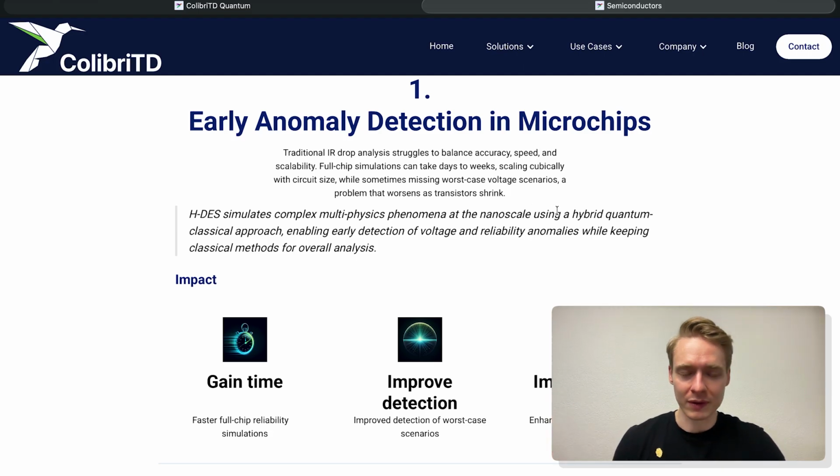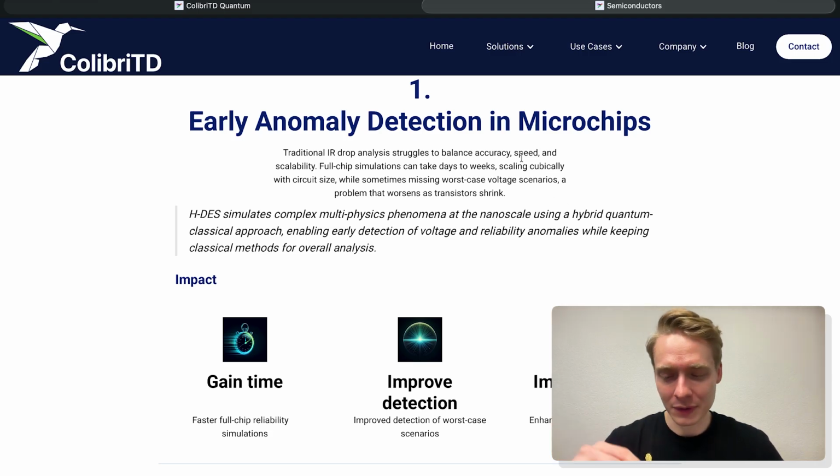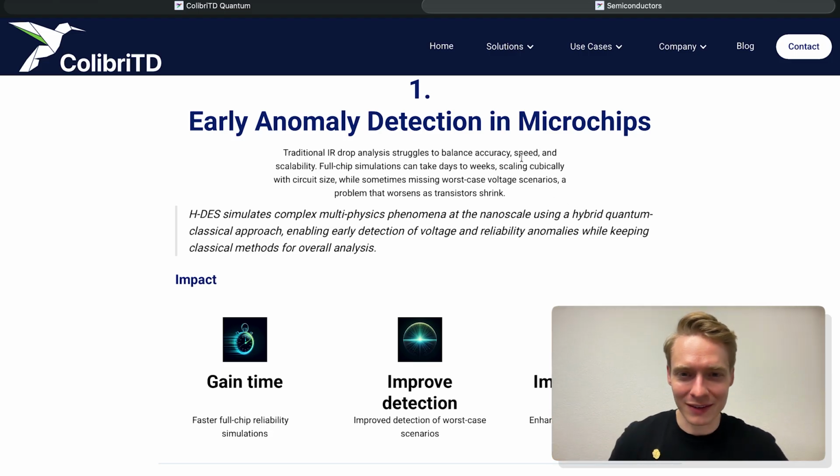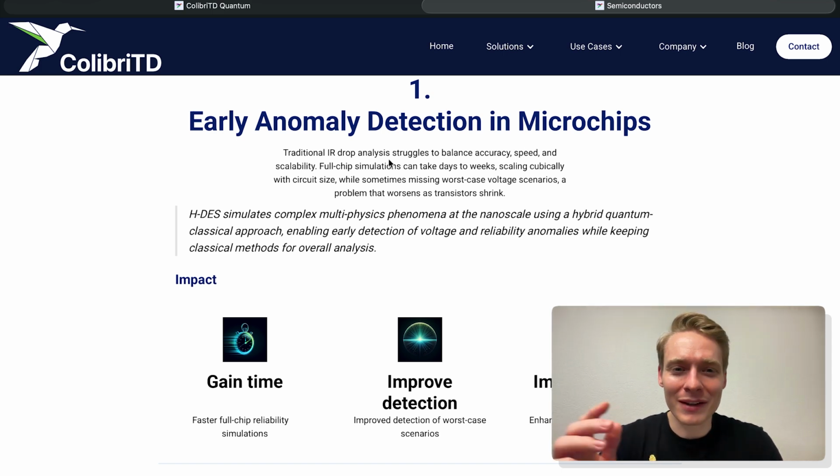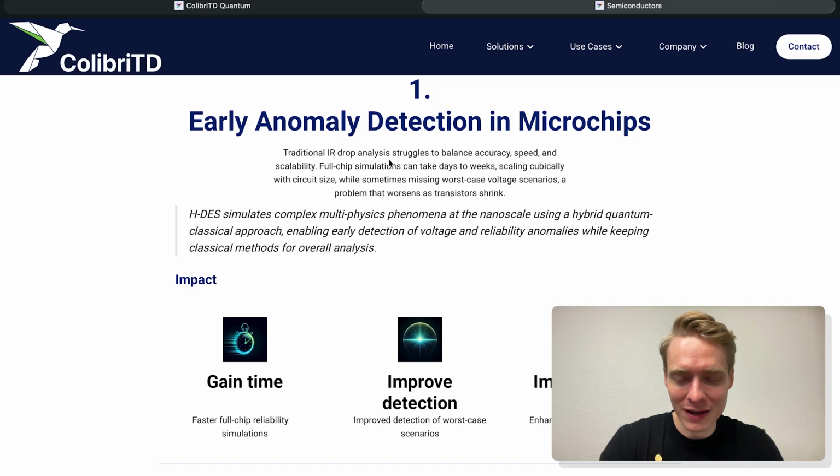So that has to do something with how the transistors actually work, the inverse subthreshold slope, and kind of how much you can deplete the channels with the gates, and how the doping actually works at these very small scales. There's a lot of details to that, which we are not going to go into. But I think what is clear is Moore's law is telling us that the number of devices still does, or maybe has, kind of exponentially scaled.